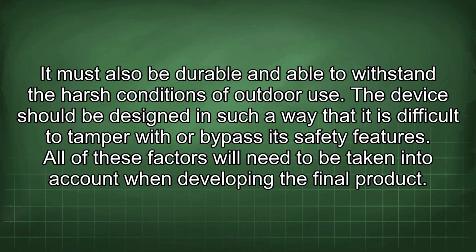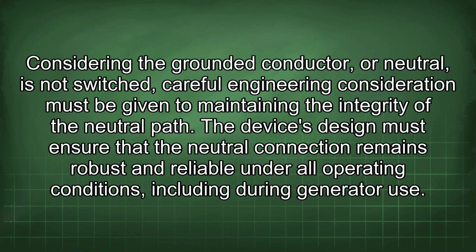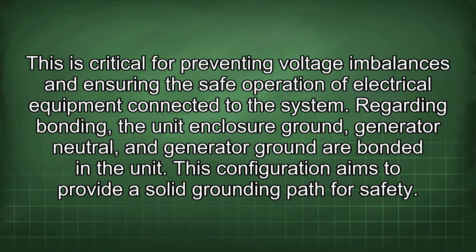All of these factors will need to be taken into account when developing the final product. Considering the grounded conductor, or neutral, is not switched, careful engineering consideration must be given to maintaining the integrity of the neutral path. The device's design must ensure that the neutral connection remains robust and reliable under all operating conditions, including during generator use.